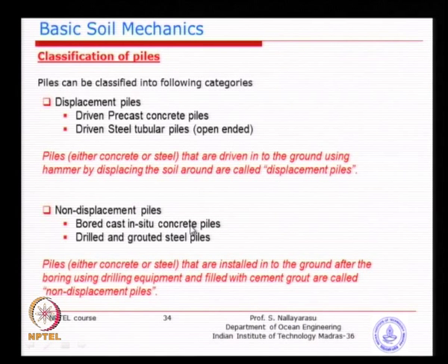So, for both cast in situ piles with and without liner, the calculation for the soil capacity is different, because we are now looking at the soil to pile interface. A steel to soil interface is different than a concrete to soil interface. Which is better? For sure, the concrete to soil interface is better because it is rough and the surface is not very uniform. So, the interface is going to give you an increased soil resistance.